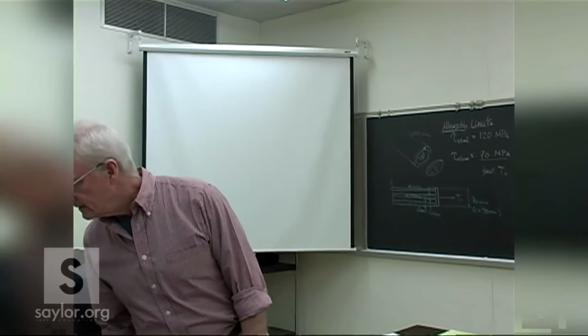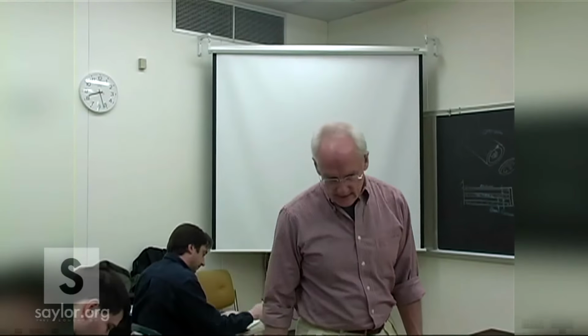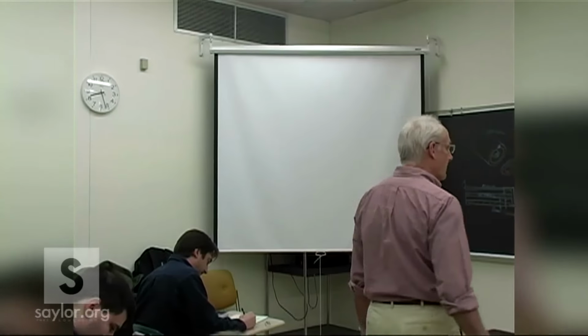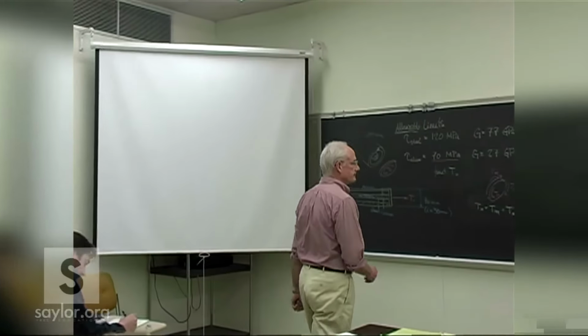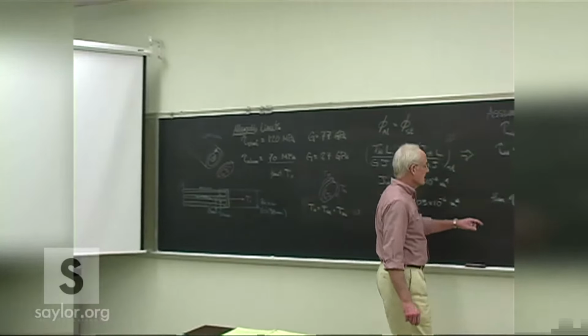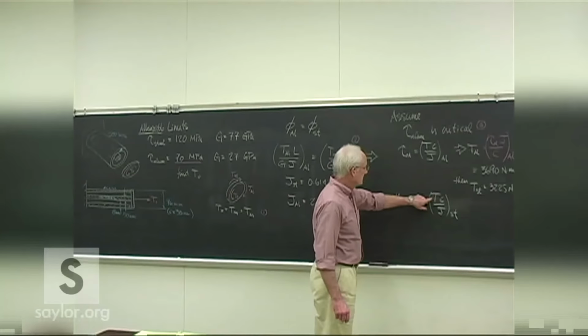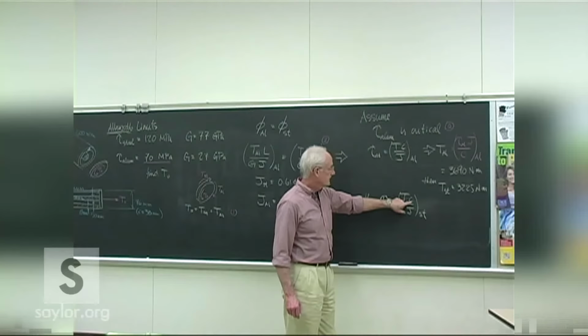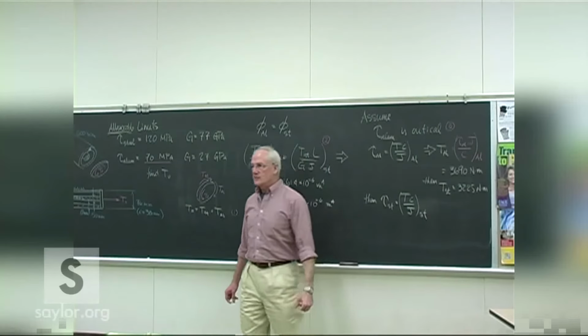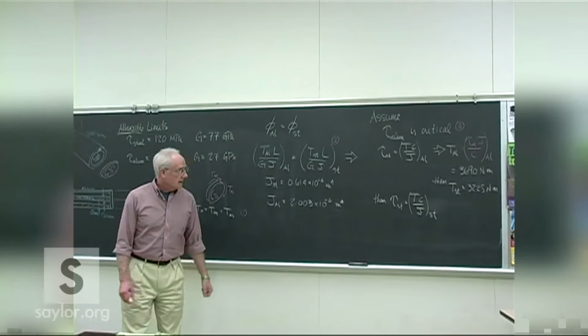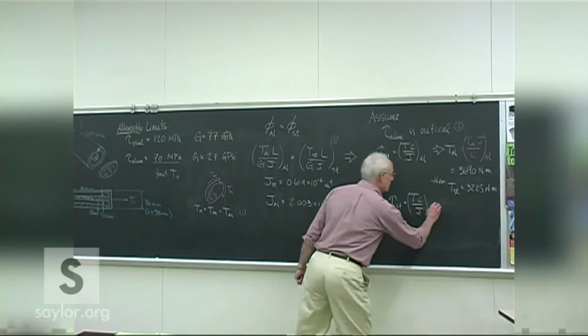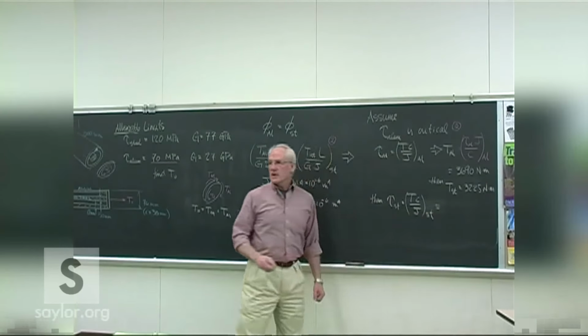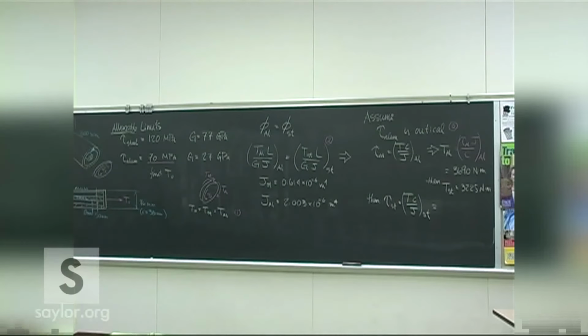Is it working, Phil? Once you've got the estimated load in the steel, then the dimensions for the steel, that should give you a shear stress based upon the assumption that we were already at the limit in the aluminum.